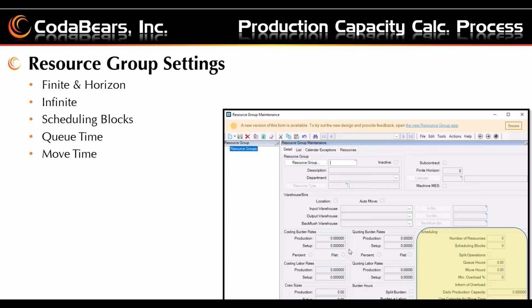So I really don't have to listen to the calendar for, say, 4 hours of paint drying. It doesn't have to run during working hours; it can run in the evening. So if the operation can continue regardless of the calendar hours, that's when we go ahead and turn these checkboxes on and off.